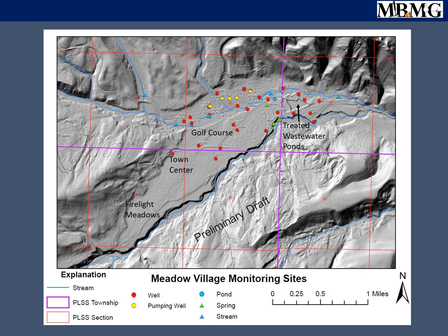And also we did some stream monitoring of the West Fork. Originally, there was an idea that the stream was gaining something like 12 CFS, but back when those measurements were made, it was before the ponds were lined, so that might have had something to do with that large gain. We actually went out at the same time of year and tried to measure the stream flows to see if we could find that 12 CFS, and no, it's more typically single-digit gains and losses.